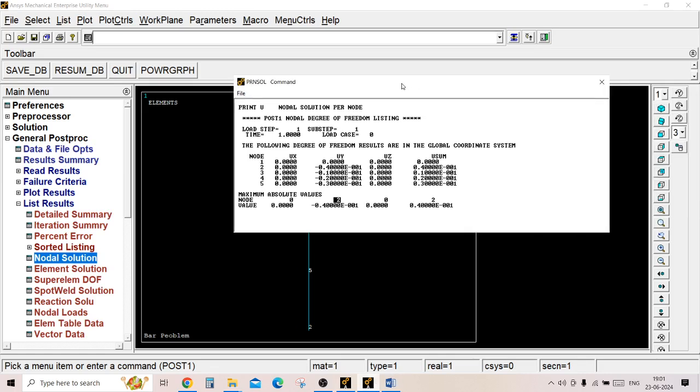Both are the same, the displacement is the same, but be sure to give the units in the same format. Everything either in kilonewtons or in newtons. Similarly, all the lengths should be given in mm or meters. If you have taken care of the units, the element type and node numbers, everything is simple.